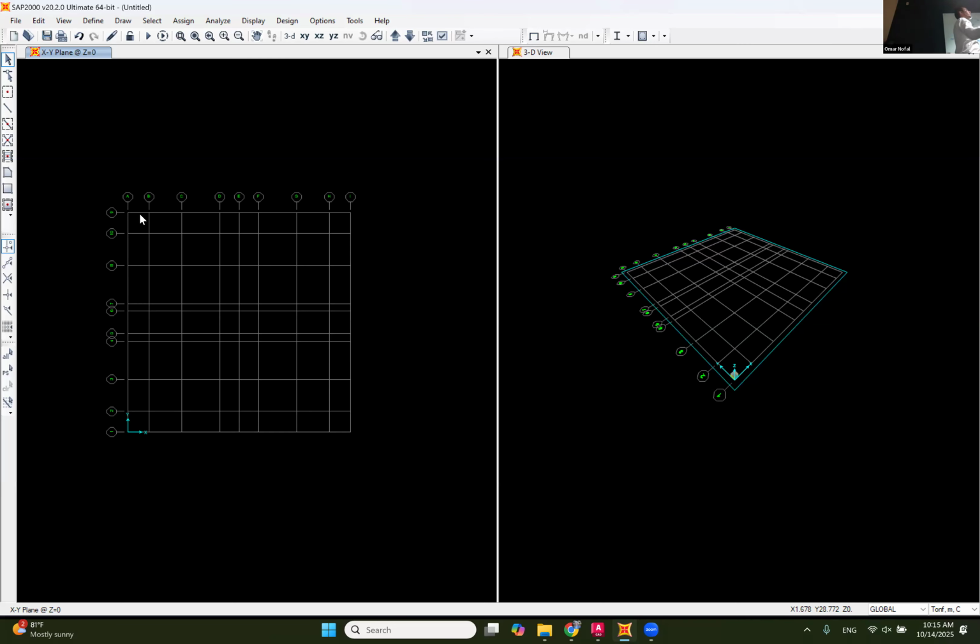So finite elements solve the structure at the points. If you have a joint here and a joint here and a joint here, these joints are where the finite element makes the solution. And then it takes the average of all the points to come up with an average bending moment. So let's say finite element tries to solve for the deflection here, and here, and here, and here. What is the deflection here? You have a hint. And here, 0 and 0.